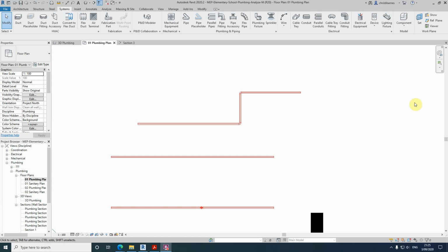The parallel pipes tool creates an exact duplicate of the selected pipe, including the system type. You can change the system type and properties before connecting other pipes into it. It might be easier to draw the parallel pipes directly from the fixtures so that the pipe takes on the correct system type. Also, you might have to modify connectors to get the pipe in the correct place. Parallel pipes can be created in plan, section, elevation and 3D views.